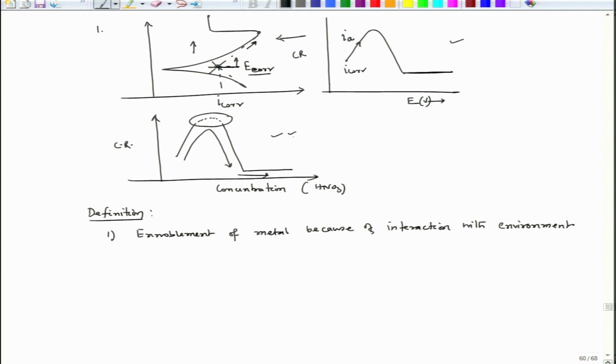If you see this graph, the corrosion rate is decreasing, and this decrease in corrosion rate is because of increase in potential. So, that means potential has gone up. We have seen that if we have two metals joined together, the metal which is cathode has a higher potential than the metal which is anode. And here remember, the cathode does not mean only the reaction related to the metallic part of that particular cathode.